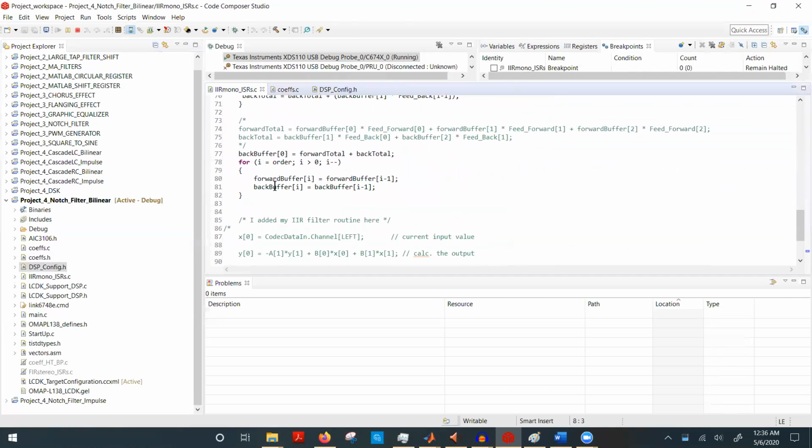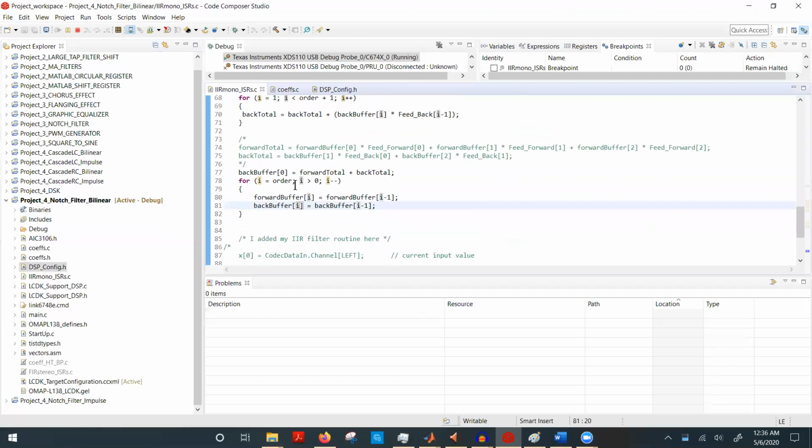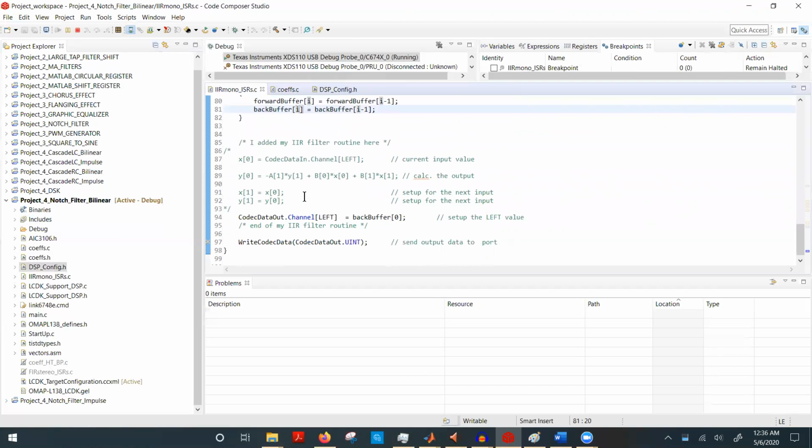But when I shift the register here, I use a shift register because I'm not proficient enough in C to confidently use pointers. So we're stuck using shift register. But like I said earlier, since the IIR filters have fewer coefficients, I can allow myself to be less efficient with my register and not suffer any consequences, unlike with the FIR filter, where every calculation matters to get the most accurate filter.